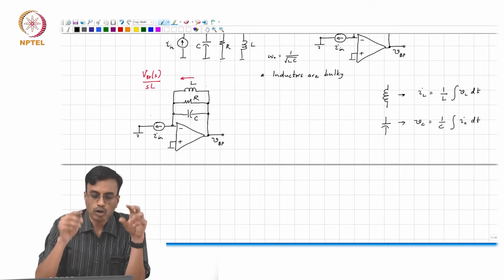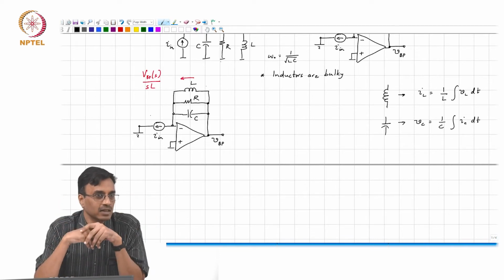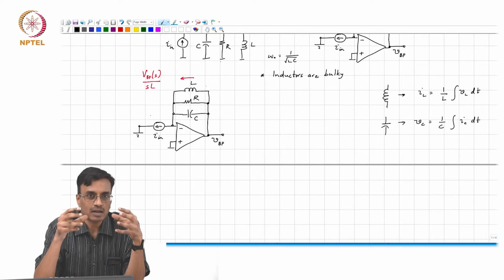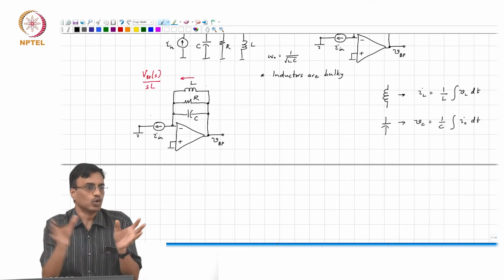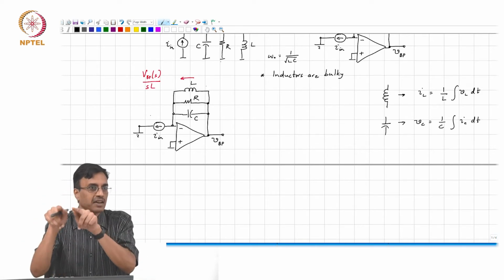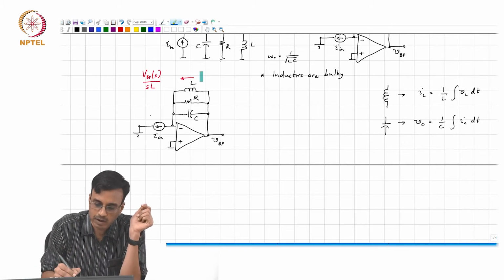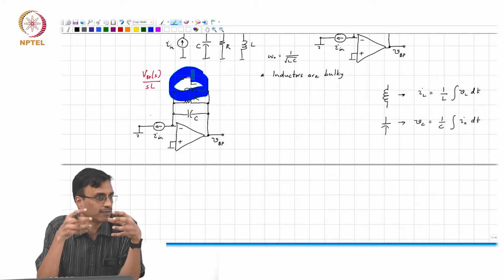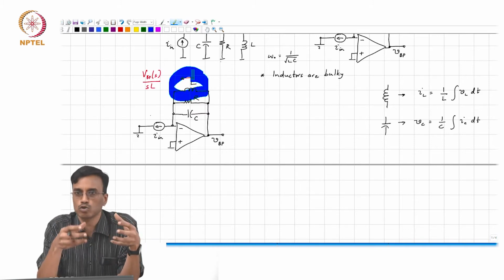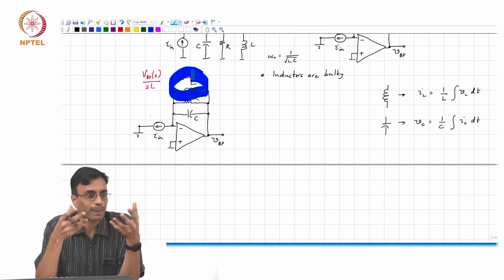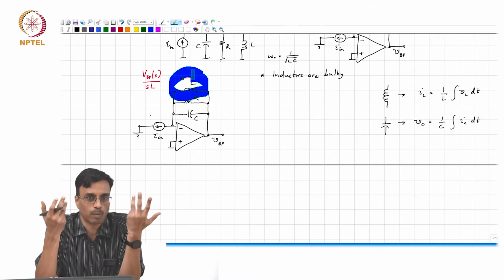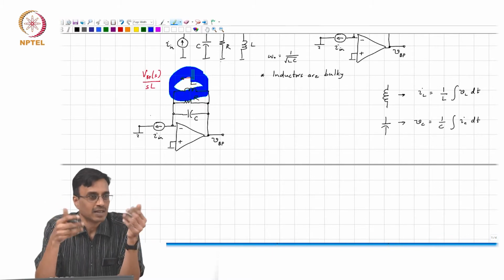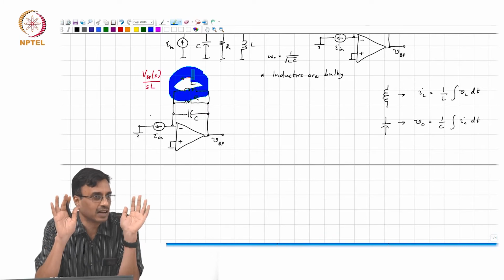So basically, we want to replace an inductor. An inductor is an integrator, right? So whatever you do, there must be some integration in that box. So let's say you put a magic box here, whose job is to do the same thing as a physical inductor without using one. What mathematical operation must be going on in that box? There must be integration inside that box.